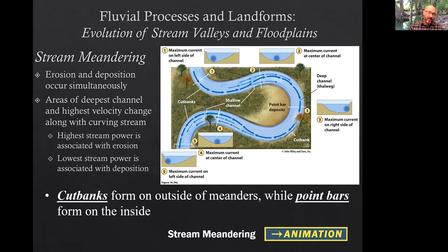Take, for example, a forested area. Those roots are going to want to hold on to that dirt and not allow the river channel to wash it away. The other side might only have shrubberies or grasses, which will be easier for the water channel, moving straight through an environment, to eat away at one side of it faster than the other. Okay? And so that causes the river to start to bend a little bit as it goes around the more difficult places to erode and cuts into the easier places to erode. And that sets off a motion.